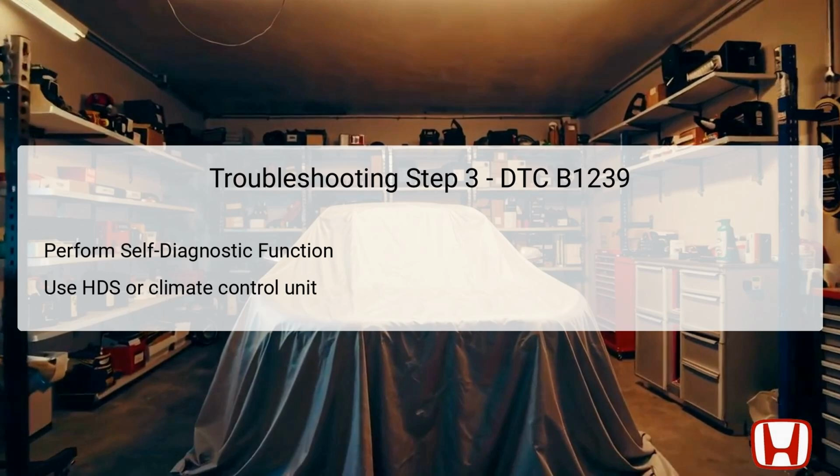By checking for DTCs again during this self-diagnostic phase, technicians can determine whether the same issues reoccur, thereby isolating persistent faults in the system. The HDS provides digital readouts and valuable codes, allowing a deeper insight into the malfunction while enabling automotive technicians to trace through the components more efficiently. This check is critical for identifying persistent or intermittent failures that might not have been indicated initially.